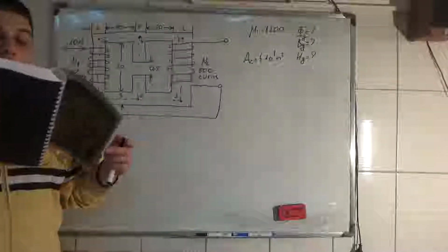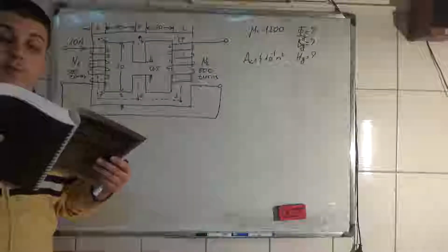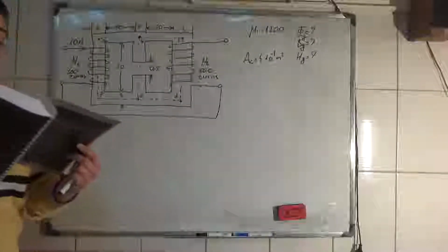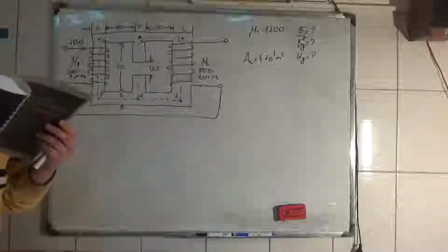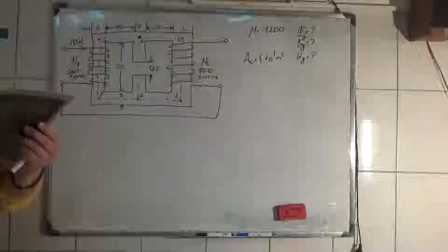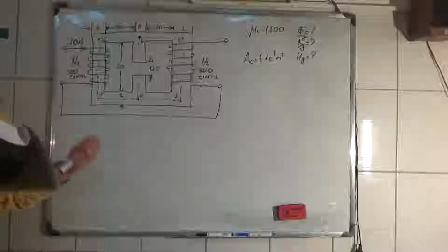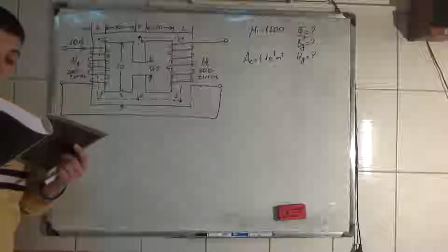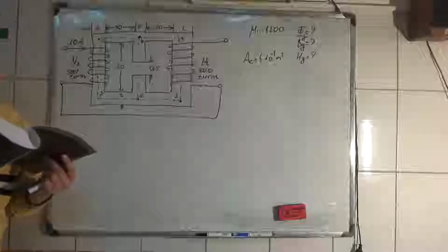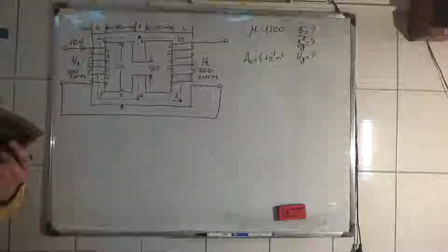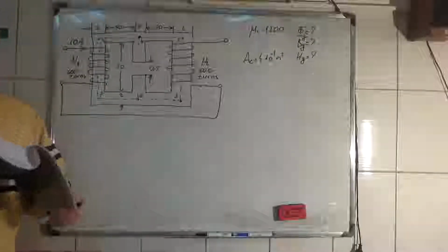So now we have a magnetic circuit here which says that the relative permeability of the ferromagnetic material is 1200. Neglect magnetic leakage and fringing. All dimensions here are in centimeters, and the magnetic material has a square cross-sectional area. Determine the air gap flux, the air gap flux density, and the magnetic field intensity in the air gap.